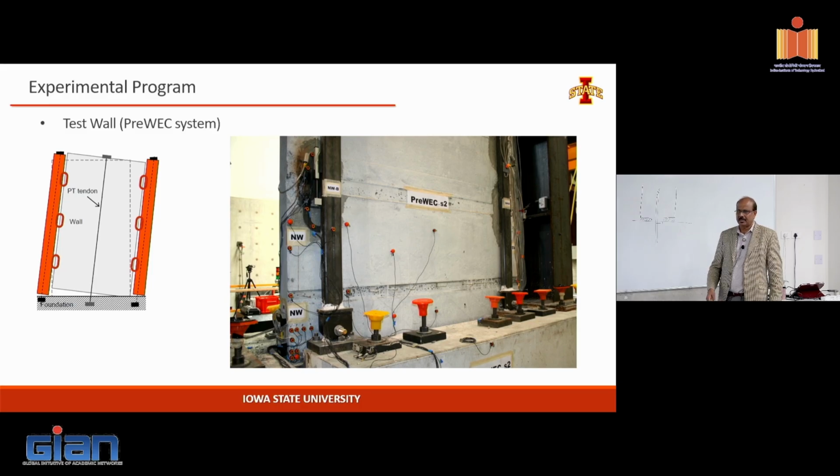I use that a lot now, actually. Even for curvature measurements, you don't need an LVDT. You can use this one. We try to use the 3D DIC. It's the same thing, a simpler version, where you don't have to spray anything. Plus, it does it in three-dimensional space, and it calculates based on the original. Once you have a crew get used to it, I just have students train the other students and keep it going.